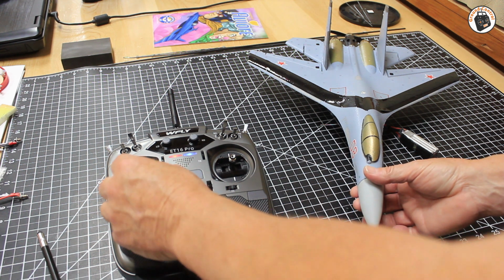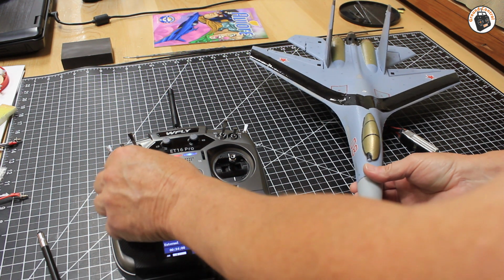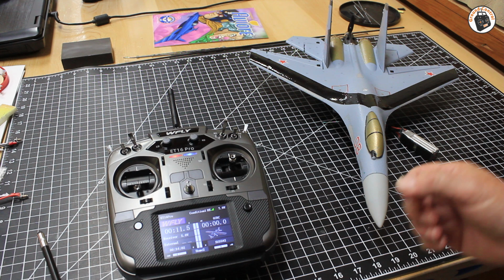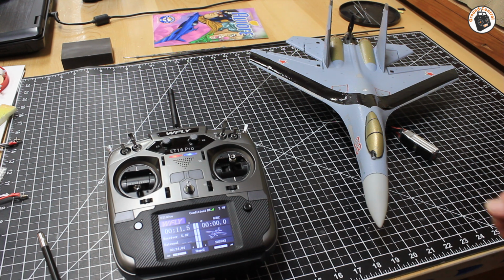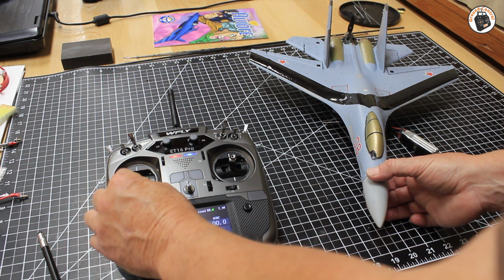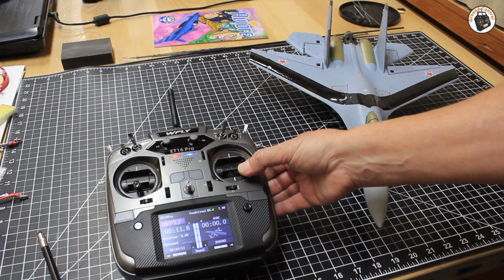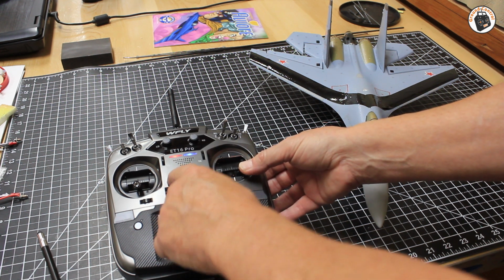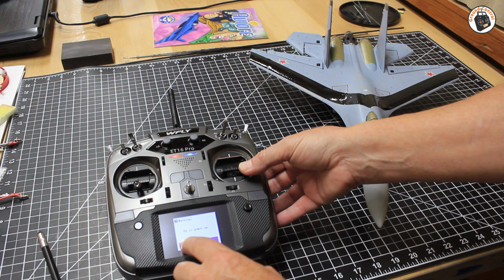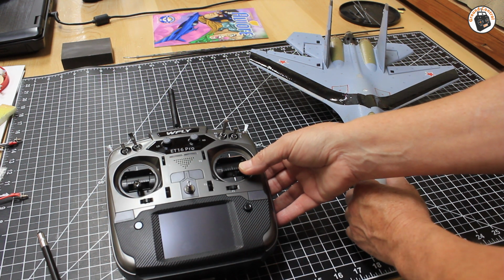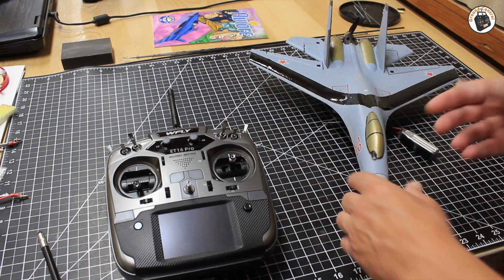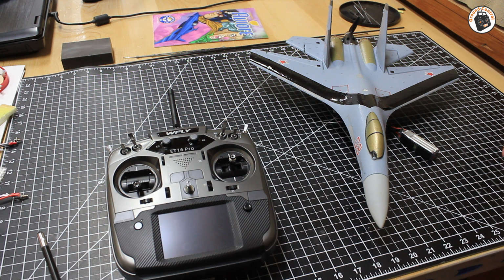All right, so now we want to take off our throttle safety switch, throttle hold on, and test our throttle. Okay, that's working. All right, so I want to give it a little bit of throttle, and some aileron and elevator, and I want to shut off the transmitter. Okay, so the control surfaces went back to neutral and the motor shut off. Our failsafe is working. Everything is working as it should.